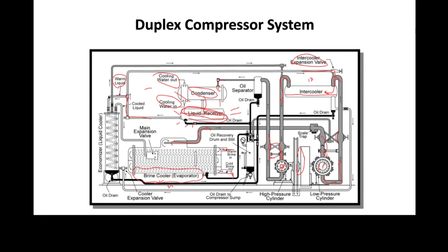So what we're going to do is take it and put it through a heat exchanger. The tubes are going to go through there, turn around, and come out, and now we've got subcooled liquid, more subcooled, cold. We've got cold liquid, and the cold liquid is going to go in, and now we're going to get very little flash gas, and we're going to have a big net refrigerating effect. But the question remains, how did we subcool that?